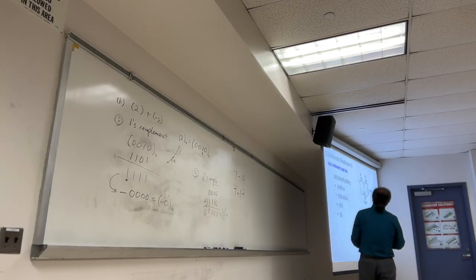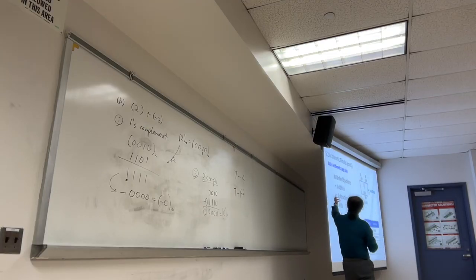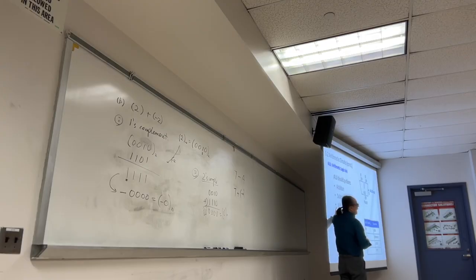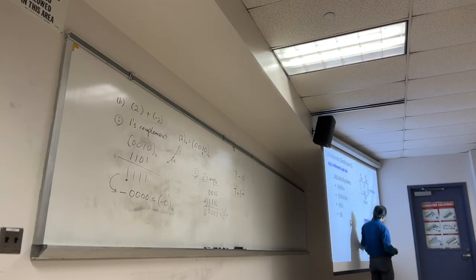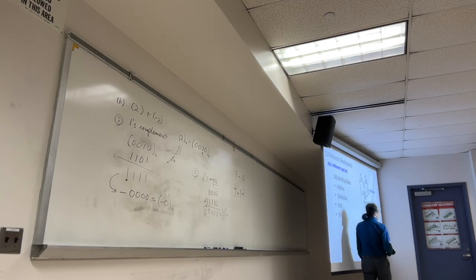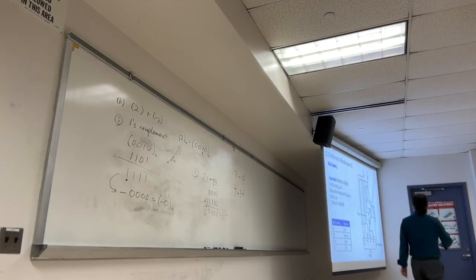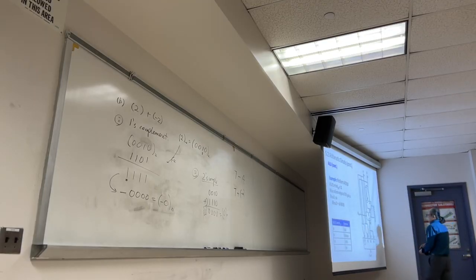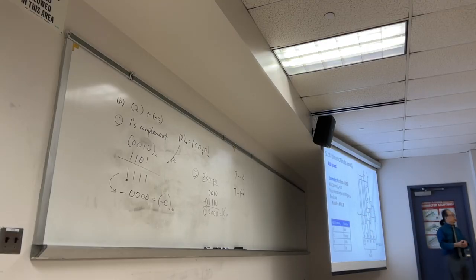In our ARM architecture, the ALU looks like this. And in the ALU, we can do addition, subtraction, and AND them. AND means go through the AND gates, and then OR them. Okay? So the ALU control is going to be 00, 01, 10, 11, for adding, subtracting, ANDing, and ORing. So here's the ALU we can design, and we will use this ALU hardware portion in chapter 7 in the architecture part.